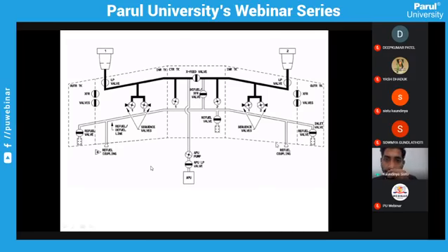But to go from here to the black line, you need a booster. You have fuel inside the tank, but you have to give a certain pressure to the aircraft engines, right? So there are booster pumps 1 and 2. Each tank has its own 2 booster pumps, because if one fails, the other will take over.